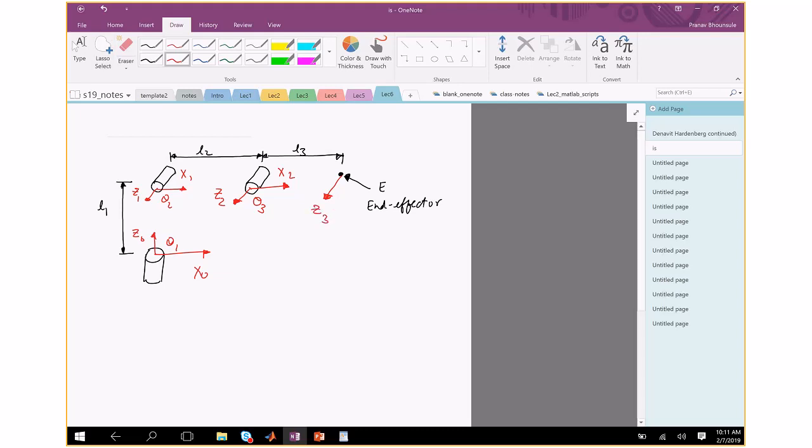And assign X. So again, you can find a relation with Z3 and Z2. They are parallel to each other, which means you need to draw a line perpendicular to the two. Your simplest choice would be such that X3 is along X2, or it passes through the origin.